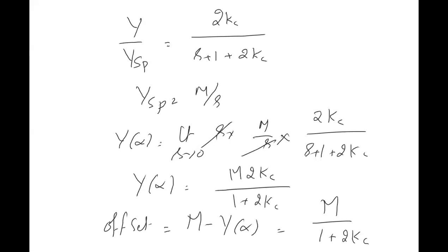So why is the expectation M? Somebody asked me the same question. We have solved the previous one. Simple question: if you change the set point of a heater from 60 to 70, you will expect your response to become 60 to 70 only, no? So that means how many units the set point changes, that many units the response should also change.